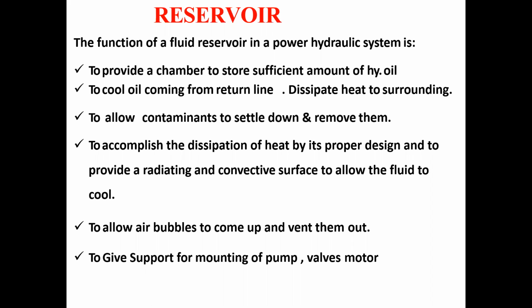Normally, if the reservoir is completely packed, at that time a vacuum may be created in the reservoir. To eliminate this vacuum, we produce a vent of air, so that air can come inside and the vacuum cannot be created.